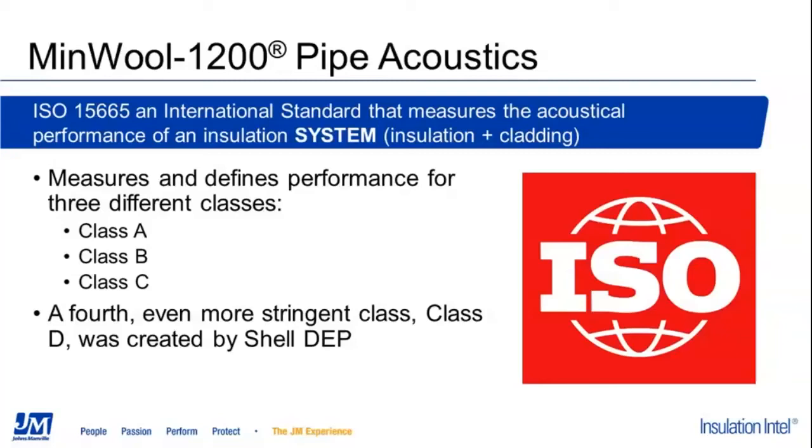As I mentioned, the standard does define not only the test methods to be utilized in determining the performance of the system, but it also creates 3 classifications for different levels of noise reduction. And those are, as you see here, Class A, B, and C, with Class A being the lowest level of noise reduction and Class C being the highest. There is also an additional Class D that is out in the industry that was created by Shell Corporation and is defined in their acoustic DEP, and that is even more stringent than the Class C. And so you do have 4 different options available.